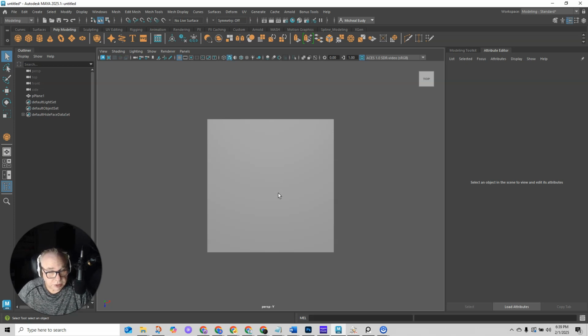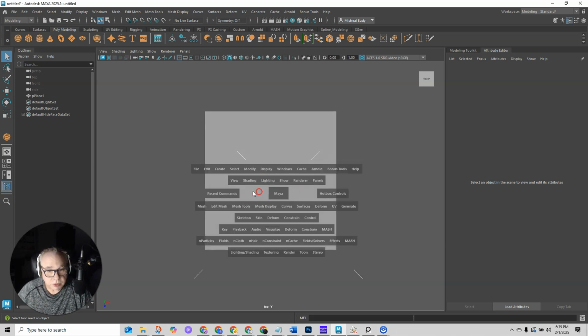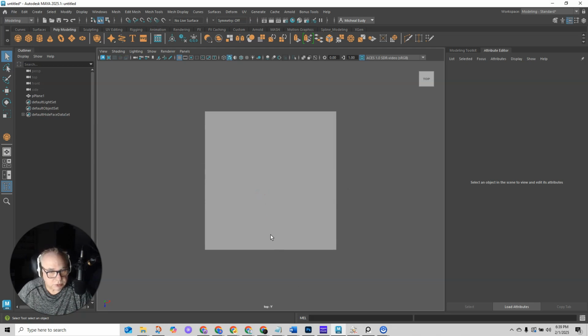That's kind of dangerous because it means that I can still be moving things in three-dimensional space, whereas when I'm actually switching to a top view, I can't move things in a three-dimensional space. I can only move them left and right and up and down. So this can kind of be misleading to students, and so I kind of tell them to turn it off. Okay, so you just right-click on it and you can click hide the view cube.